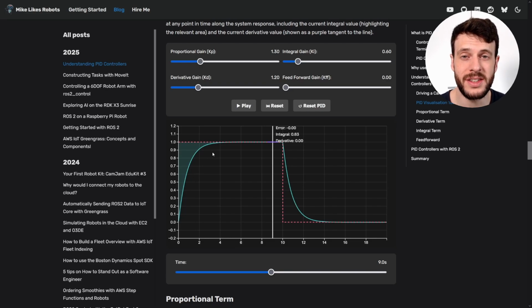So what we can see here is that different PID parameters, Kp, Ki, and Kd, need to be tuned for different systems. In this system, these values give a good response. They give a response that is fairly close to the set point. We can't get a pure vertical because it's modeling a system that can't accelerate infinitely fast. So it has to curve up and meet the set point as we want it. Now that we've got the parameters tuned fairly well, we can start to see what effect each of them has on the output of the system without the oscillation that was going on before.